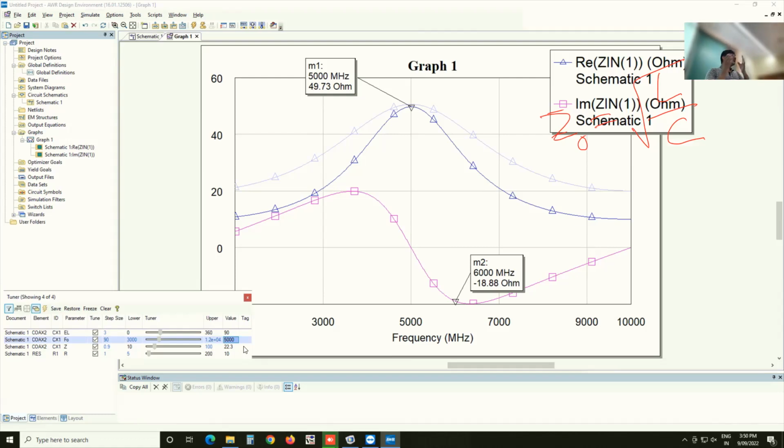So the number of sections you use will determine how smooth your changes are, and that will determine how broad the bandwidth is. But it also means that the overall transformer length will become very long. In a practical situation, you might worry that there are too many sections. In reality, these transmission lines will have losses, so that can affect things. You have to make these compromises to decide which choice to make. Those things are often called continuously tapered transformers.